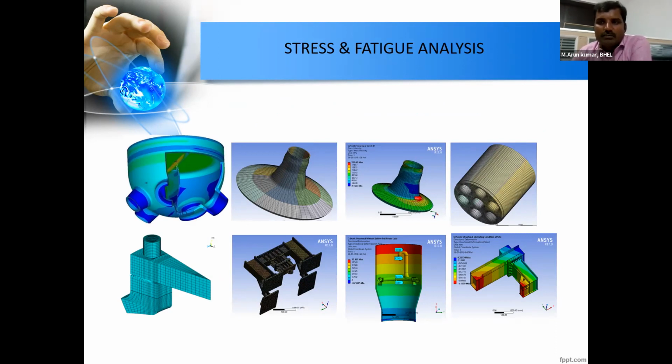For example, if temperature is involved, we select either a 2D or 3D element with temperature as a degree of freedom, a scalar quantity. Then we couple these results with displacement as a degree of freedom, a vector quantity, in another 2D or 3D element. Here we are doing everything through APDL programming.